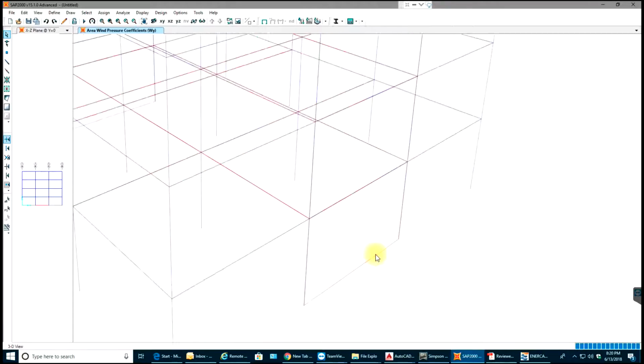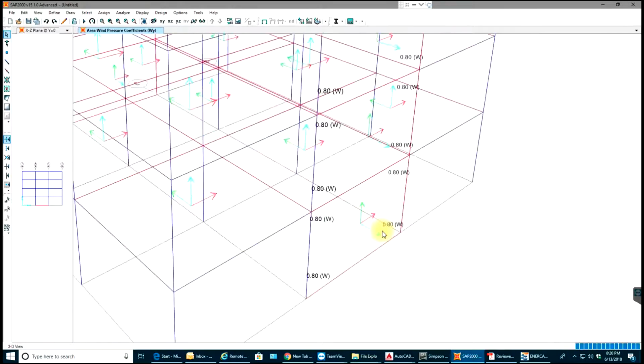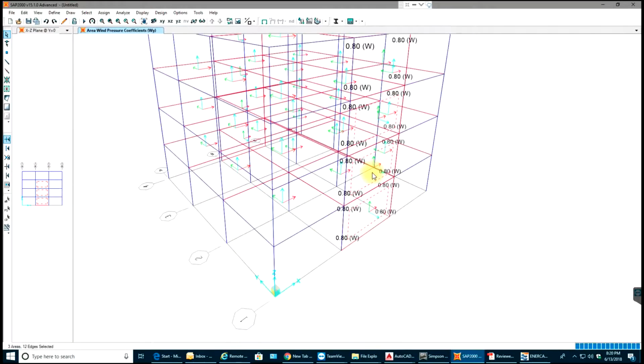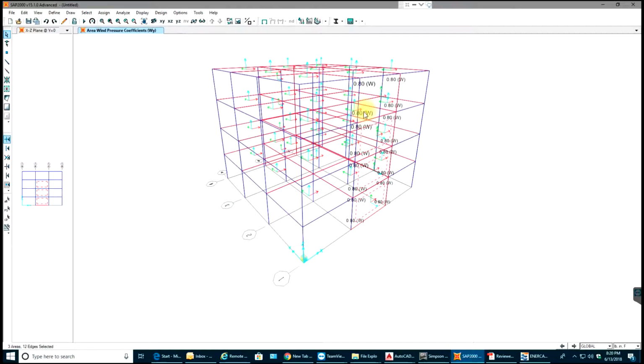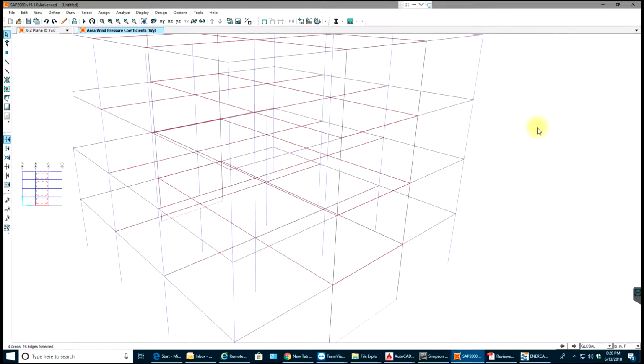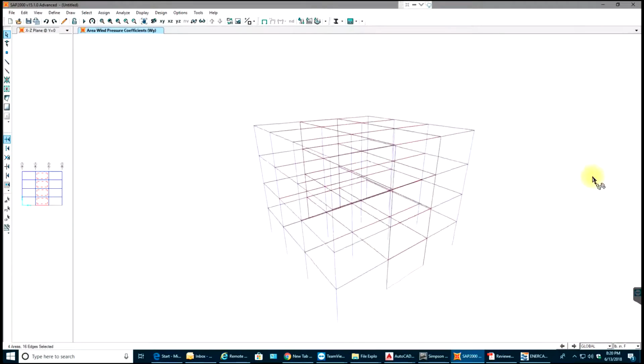So the CP coefficient generally acts in local 3-axis direction. So now in order to make it act in y direction, instead of selecting 0.8, I need to enter -0.8.